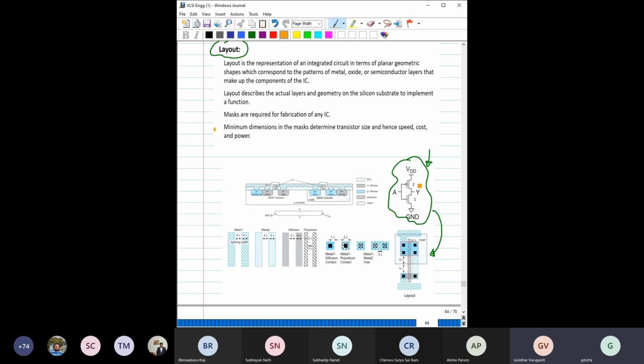So just to give you an idea, here you can see the PMOS width is 2, NMOS width is 1, because we know the mobility of electron is 2 times that of hole. So to make the resistance of both pull up and pull down network equal, we have to make the width 2 times. So you can clearly see this is actually PMOS. This is the tap part, for the contact part. Okay, this is the polysilicon part, this is the polysilicon gate.